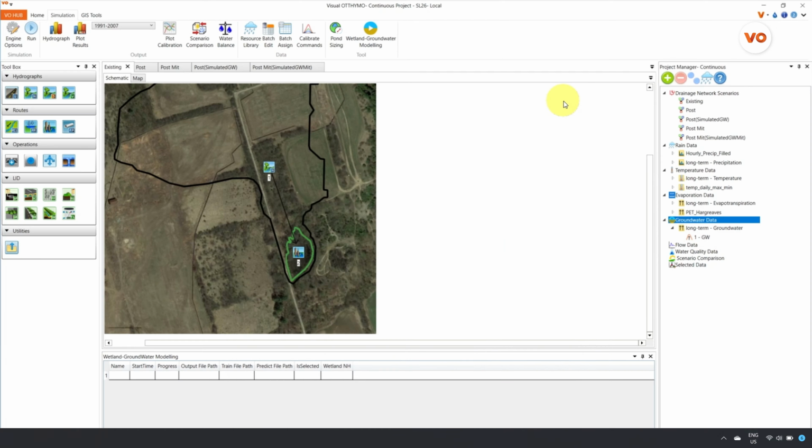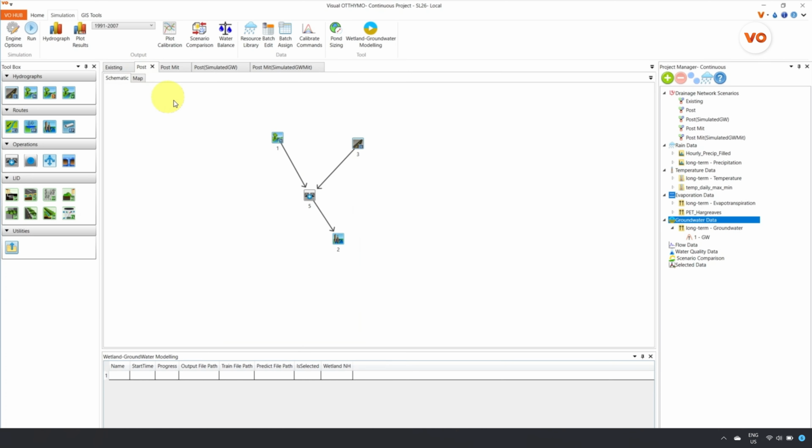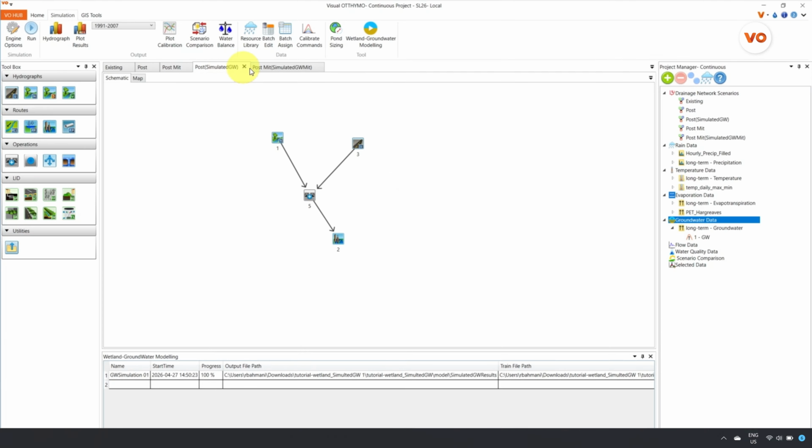But after development, things change. Land use, inflow, and recharge patterns all shift. That means the old groundwater record no longer represents reality. So to model post-development accurately, we need simulated groundwater data. We'll look at two scenarios. First, without control, where part of the catchment is developed, and second, with control, where additional infrastructure, like a roof area and a roof reservoir, is added. We'll compare results between the traditional approach that uses recorded groundwater and the new method that uses simulated groundwater.